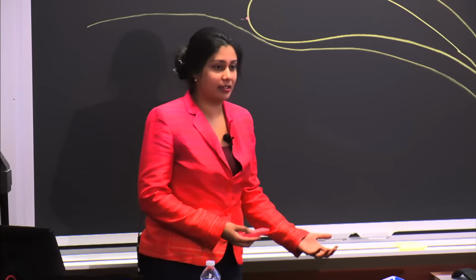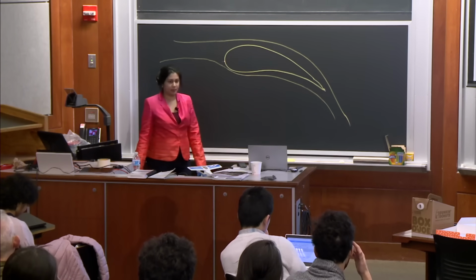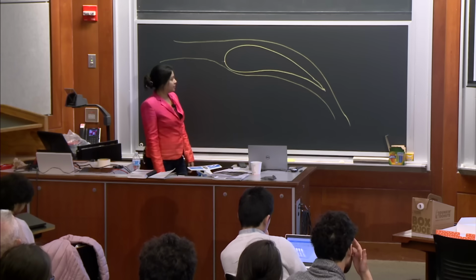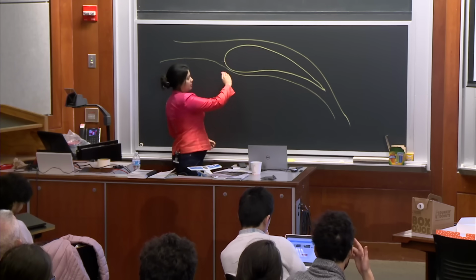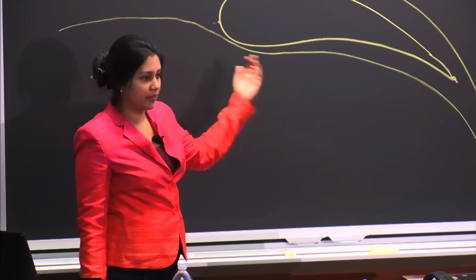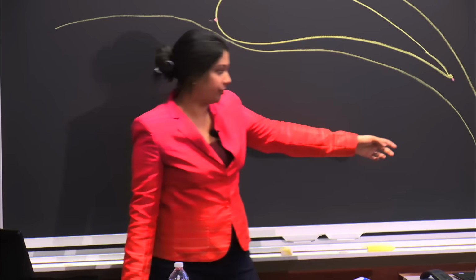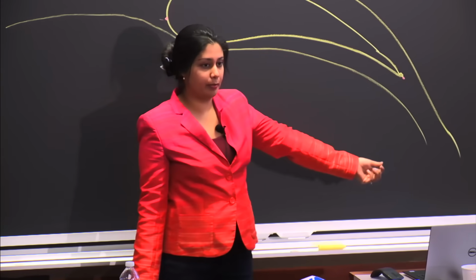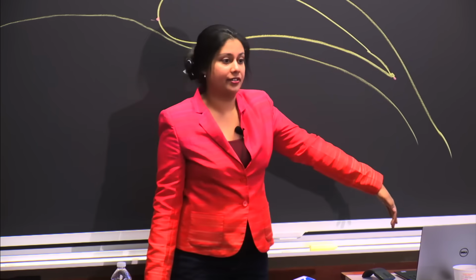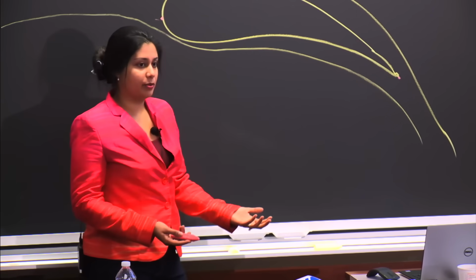But in this false theory, equal transit theory, they say that you have to reach the bottom at the same time. They also say that there is more distance basically to cover because of the shape of the airfoil. So in order for the molecules going over the top to reach at the same time as the molecules over the bottom, they have to go faster. And so since the air is moving faster over the top than the bottom, that's what creates lift.